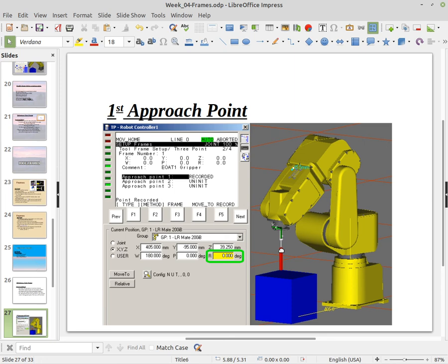With the user frame, when you know that origin and the X and the Y, those points were defining that plane, and that origin point is the 0, 0, 0 for that user frame. But for a tool frame, your frame of reference is that tool, that tip of that tool. And so it doesn't matter exactly which point you pick in space. Notice here that I placed the robot here, and I'm just highlighting that my roll is 0 here.